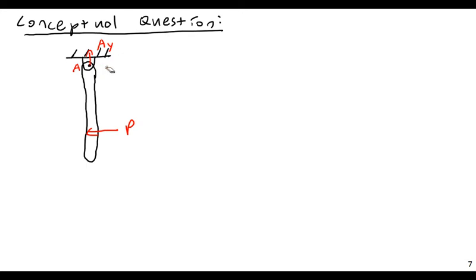Well, actually, no. That would be a statics problem, so we're not worrying about it being constant. But there might actually be some AX there. It wouldn't be equal to P if it was accelerating, but there could still be some AX. Actually, never mind. I think AX would be equal to P. It would not prevent rotation, but it would prevent overall translation. That would make sense. Okay, anyway, the question I have here is, which of these forces, if any, do work?